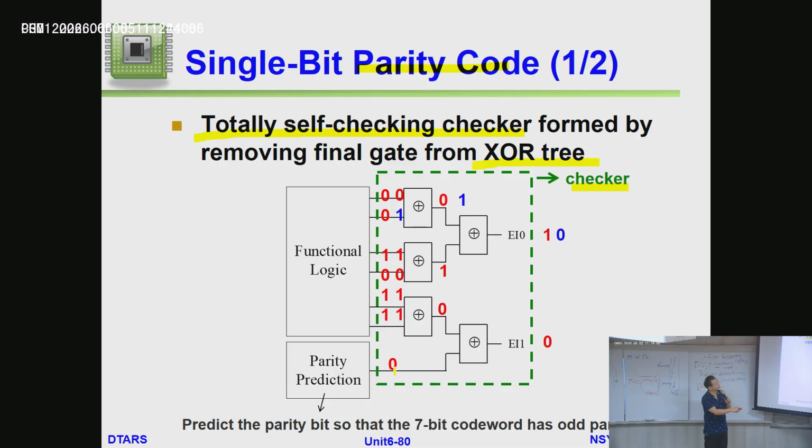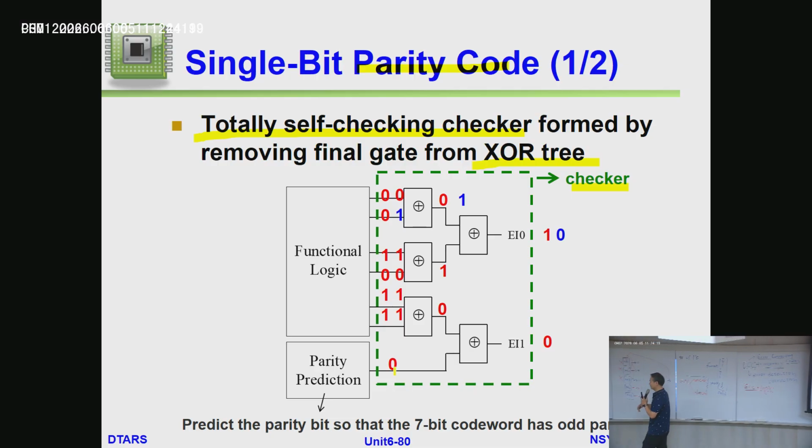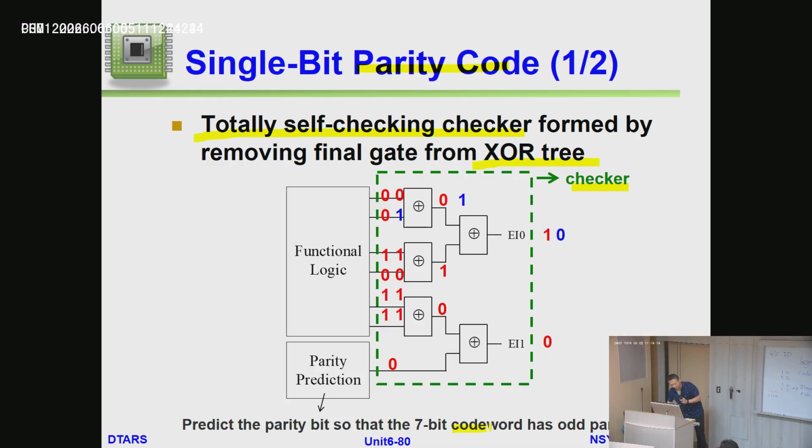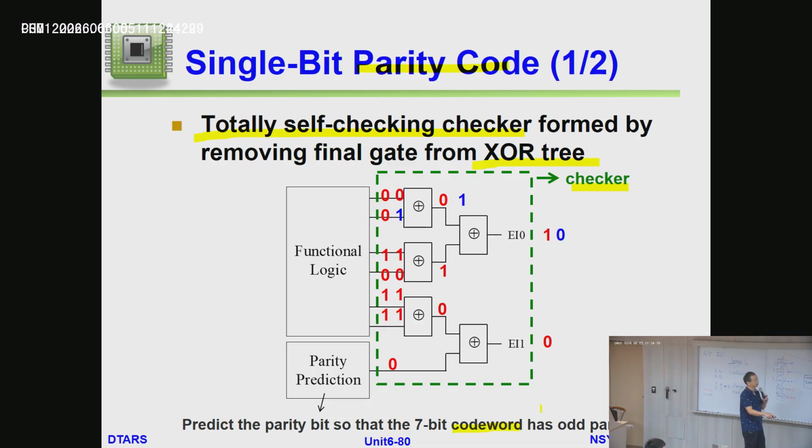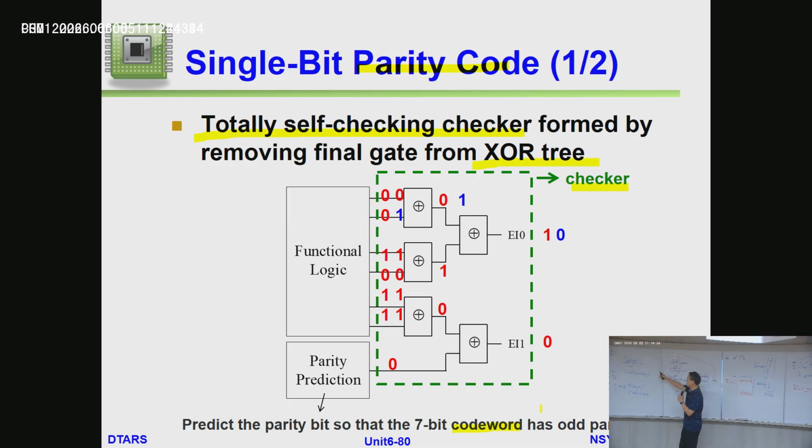For this original information, for example, these 6 bits, if we have an additional 1 check bit, then this 7-bit information we call a code word. Because this process is an encoding process, we should have these keywords. After encoding the information, we call it a code word. This code word will be legal or illegal, so we use legal and illegal to differentiate whether there are some errors.